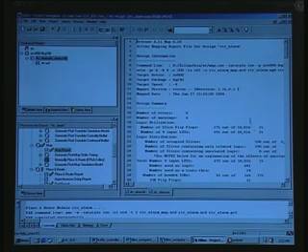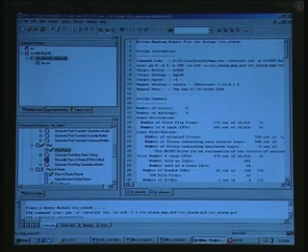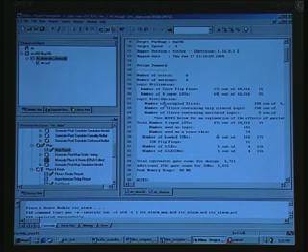The device that we have used earlier was also the same device, say 800, because that happens to be the board that we have. And similarly 4 input LUTs that have been consumed is just 641 out of 18,000 and odd. Let us not go into the details of this, which we are going to cover in the next application when we take it up, and it is sufficient to say that it merely reports the gate count. For example, here it reports gate count, say 7,000 and odd, and JTAG IOBs, and a part of the gate count we can take, and all are reported only in this map report here.